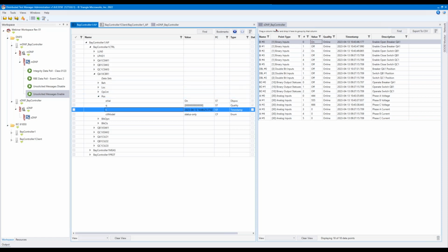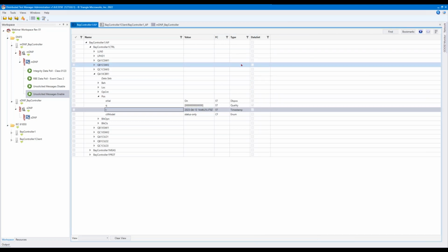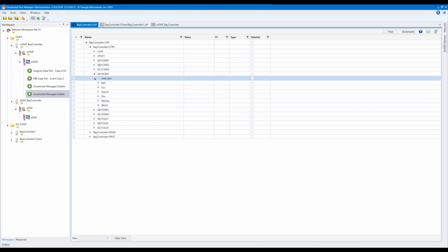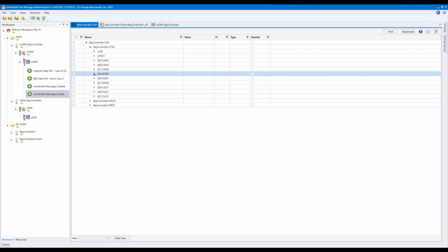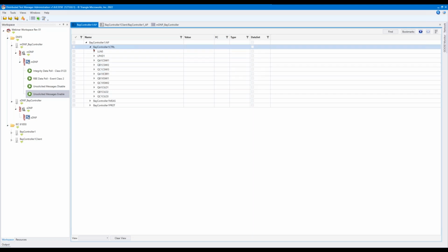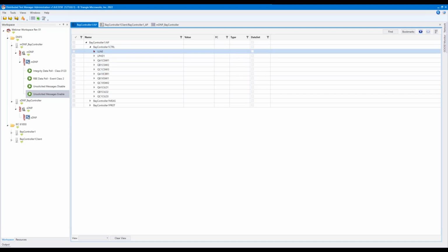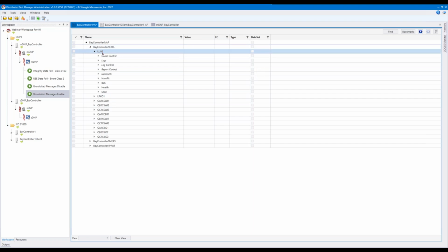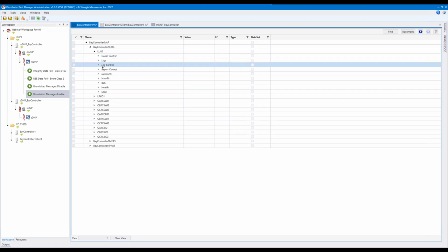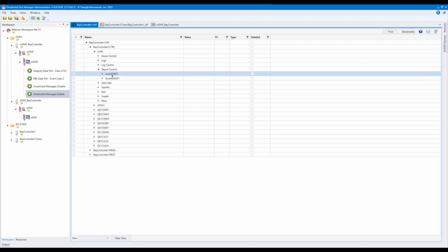Now, before I go over to my 61850 client, I do want to point out how we're going to categorize our data that's going to be sent. So for DNP3, we had classes, and we had a limit of 3 classes that we could place our data into. For 61850, the equivalent concept might be called report control blocks or GOOSE control blocks, as Christoph mentioned. So to show those, I'll expand out my logical node LLN0, and then we'll open up the report control section. Within that, I see BRCB stat, so that's buffered report control block stat, and mesh for measurement.